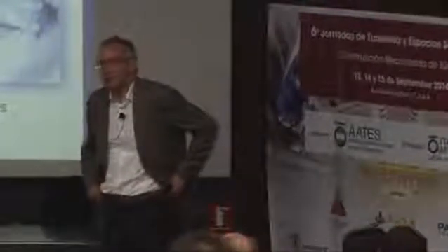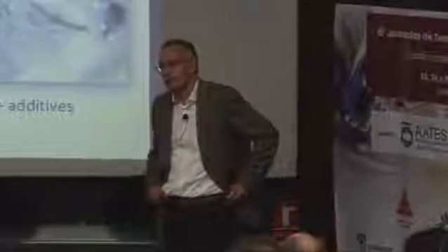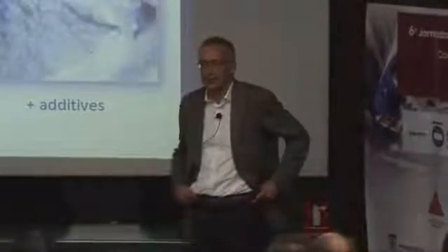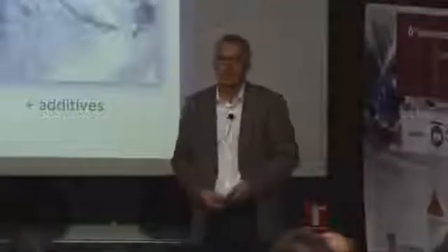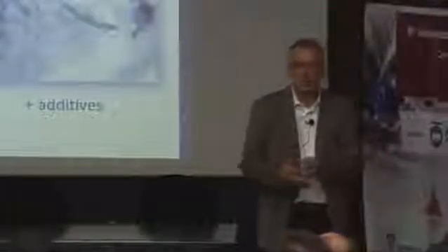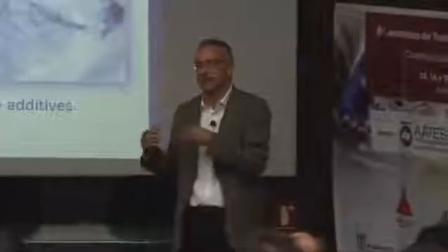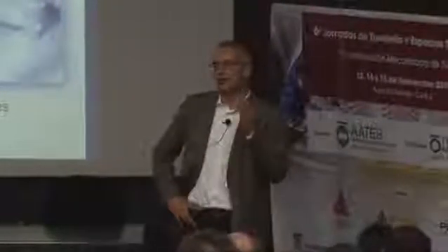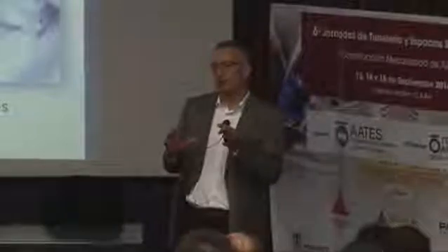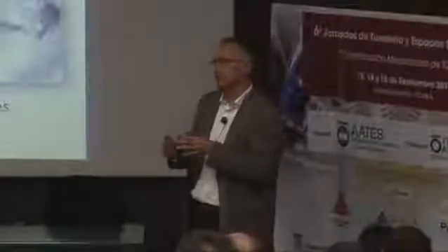With an EPB TBM, it is a little bit easier, because at the end you have to control how the foam injection reacts with your excavated material. You can adjust the foam to your material. You adjust this in the beginning, before you start with the EPB operation.